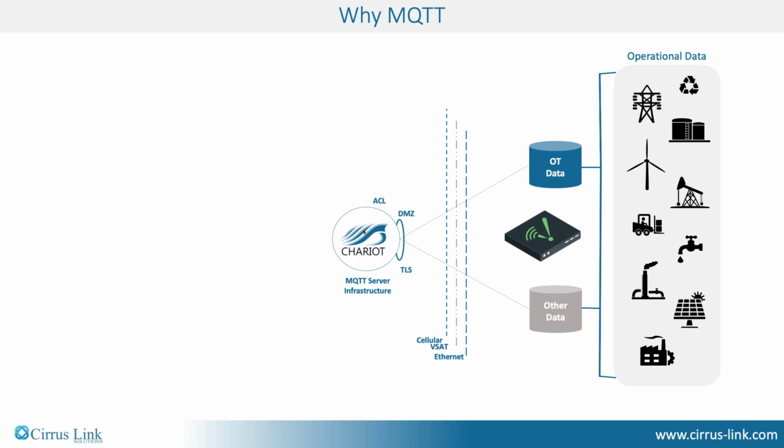Okay, so now we've accomplished the decoupling, and with MQTT and Sparkplug, we've got this capability of providing a single source of truth. Now, from an operational standpoint, we can plug the Ignition platform in with MQTT Engine, connecting to that MQTT infrastructure, and discovering all of the information that we're interested in. What's very unique is that I can plug another Ignition system in, or anybody that's MQTT capable, and they can subscribe to that information as well. So we have customers that plug this in and use that as their development system, so they can develop with live information.